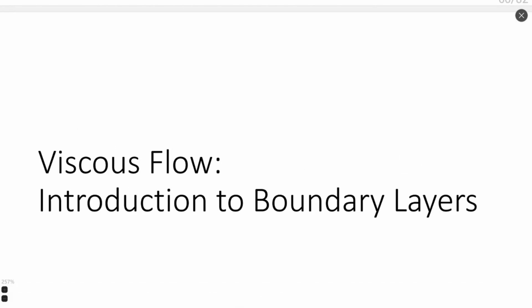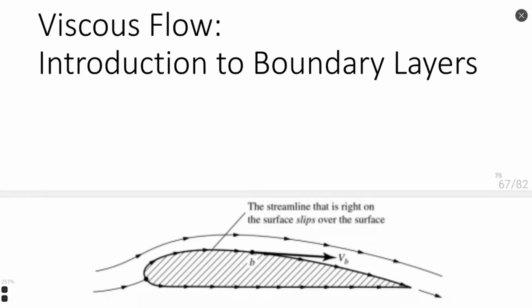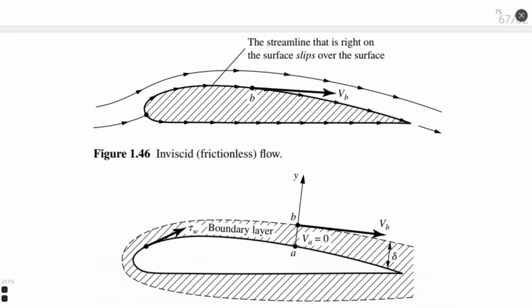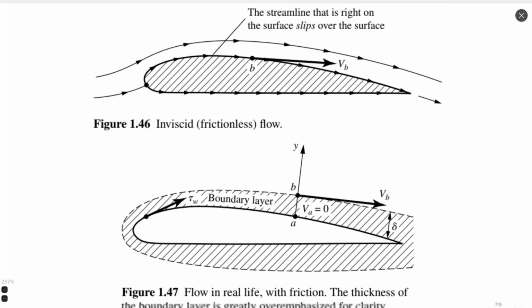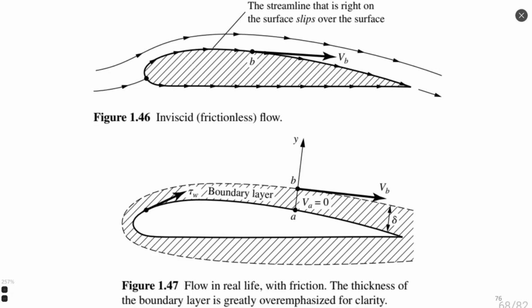And the last thing, very important, also an introduction to boundary layers. You will probably already know what a boundary layer is, in Portuguese, camada limite. Right, and you studied it in fluid mechanics, I'm sure that you know, just to refresh your memory, not to explain from zero, right? Boundary layer is a structure that deals with change of velocity. Change of velocity happens near the body when flow interacts with the body.